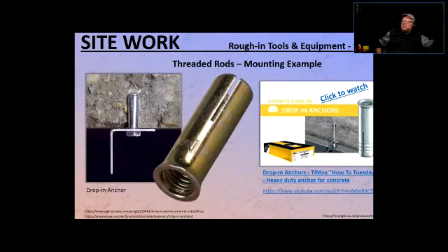Hilti gun is an example of it, and you can get attachments to it. So it's a quick lock and load. The drill bit has a die to it. So you just snap and turn, whatever you have to do, and you drill the hole, and then you undo that and lock and load another attachment. So instead of having the driver and hammering it in, you just quick snap on the other attachment and go zzz, and that thing does it for you instead of hammering.